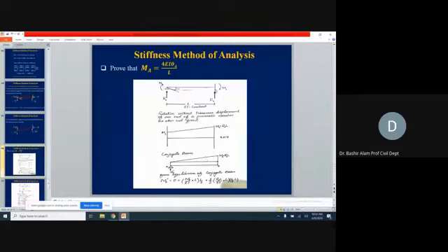Now at the top, if you see, we have joint A at the left support, joint B at the right support. Joint A, we make it a hinge support, and joint B, we don't allow any translation and any rotation there. So this is a fixed support. So rotation without transverse displacement at one end. We are not allowing any translation at A, but we are allowing only rotation here, which is shown here. The rotated shape you can see, and you can see theta A also.